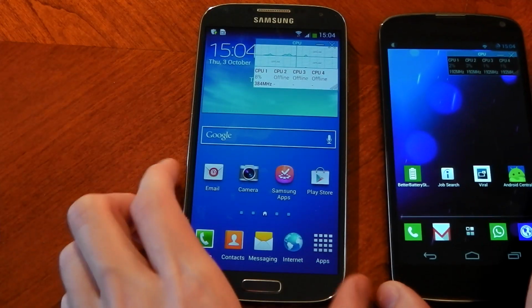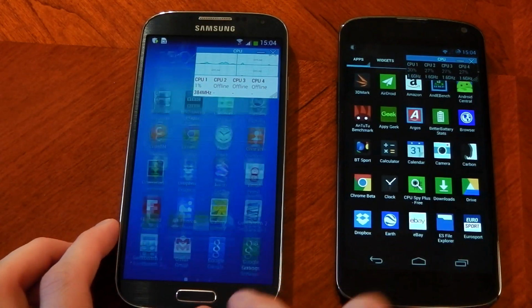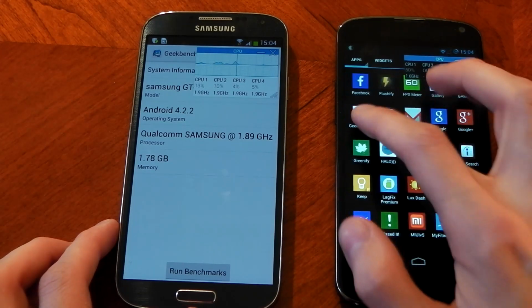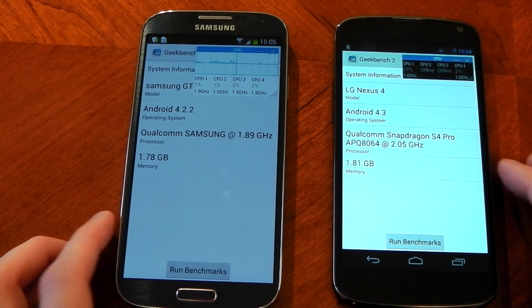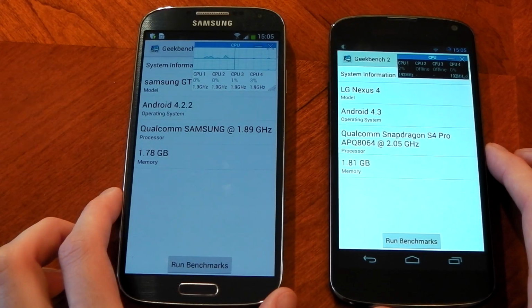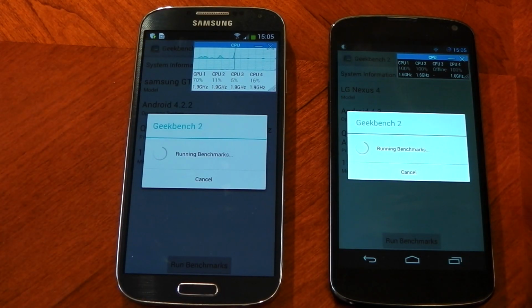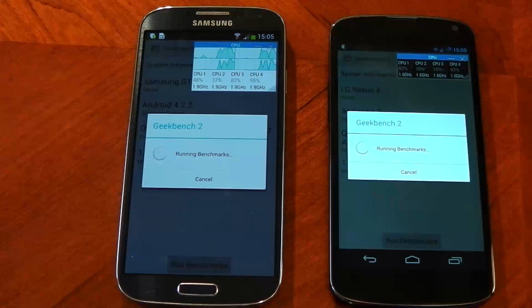So you're probably wondering what the advantage gained is. Well, let's run this on the Nexus 4 and Galaxy S4 and watch the cores when I press start. Now the Galaxy S4 is obviously already maxed out. The Nexus 4 takes around 1 to 2 seconds to reach all cores online, so the Galaxy S4 gained an advantage. It's already running at full performance constantly, whereas the Nexus had to wait for a significant load to turn on its cores, which obviously takes a little bit longer, so it's going to get a boost in benchmark scores.